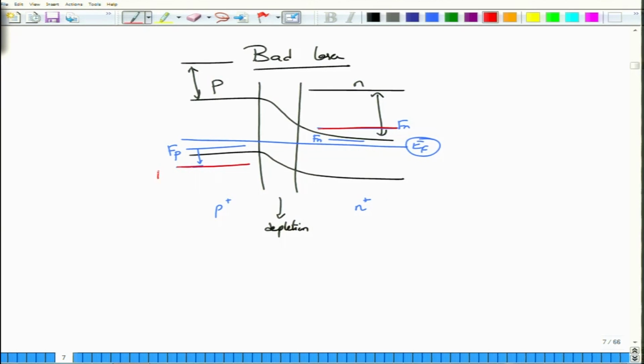To form the laser, it is not sufficient for us to create just some amount of electrons and some amount of holes in the conduction and valence bands. We have to dope them so heavily that the quasi Fermi levels for the holes and electrons actually fall into the band itself. Of course, in that case the Fermi levels are not going to be aligned in the non-equilibrium case, and the other condition is that the barrier height also reduces, because you have started to forward bias the junction.